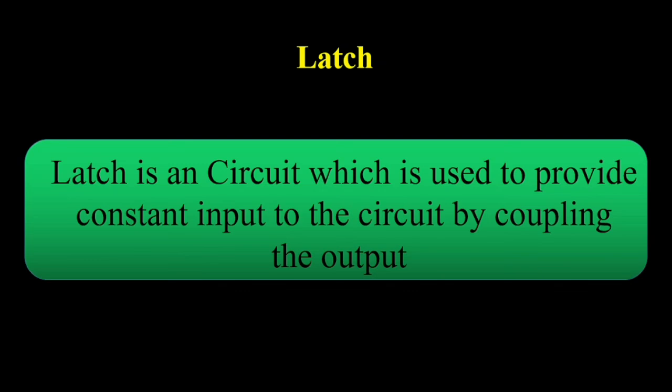For example, take a normally open push button. For getting the output we need to push the button, but we can't push that button for a long period of time. For that we can use the latch. So here when we push the push button we will get the output. By taking that output as a latch we can get a constant output. Nothing but in latch we can get a constant output from the input. So this is the function of latch.